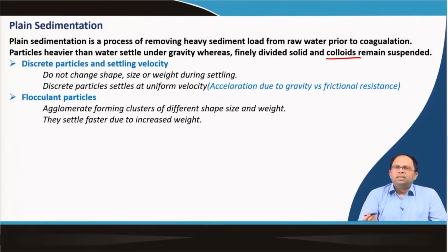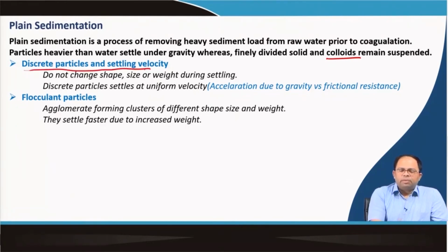So, the basic process of sedimentation is used both in plain sedimentation as well as coagulation with sedimentation. In both cases we use this process. So, usually in plain sedimentation we have discrete particles, and we are also aware of their settling velocity, that means at what speed they will settle, and then we have got flocculent particles as well. So, this is when we mix coagulants.